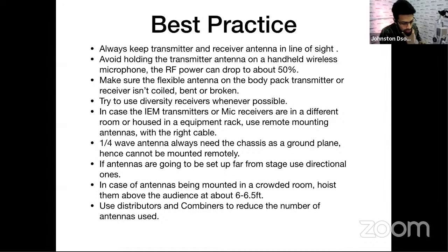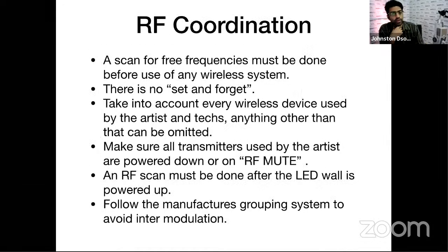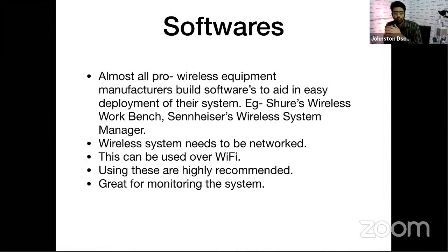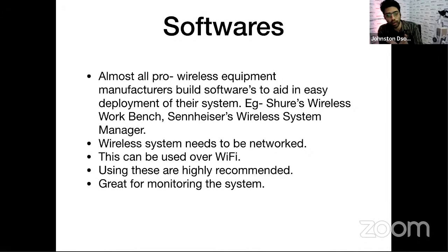All this is hardware, what about software? Yes, software is there. Software is basically RF coordination. I spoke about RF coordination, how to scan the frequencies. Most of your pro systems will give you some software which is going to aid you. It's not going to solve all your problems, but it will help you in solving a problem. For example, Shure makes Wireless Workbench, Sennheiser makes Wireless System Manager. It will help you to scan. You can network this system.